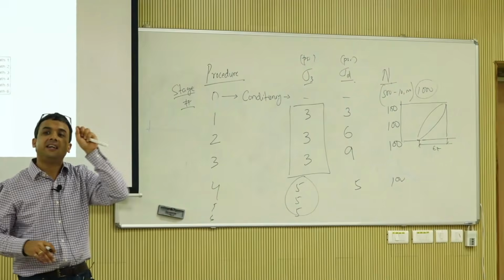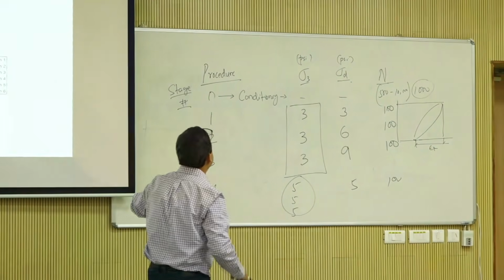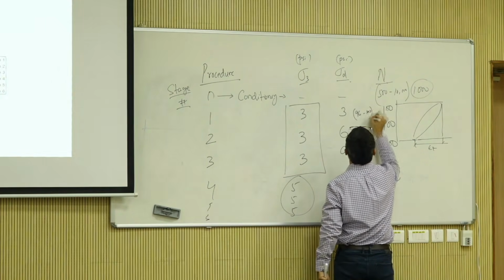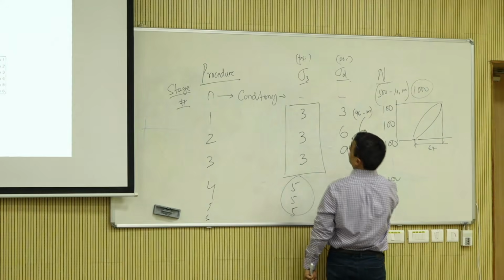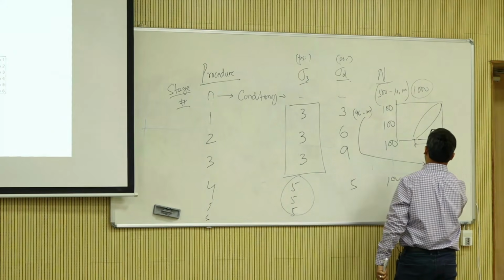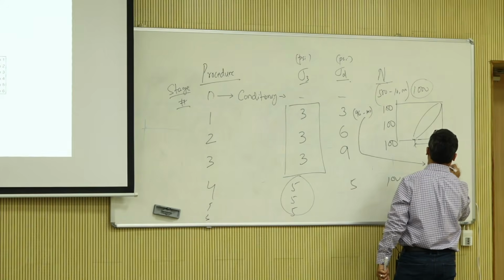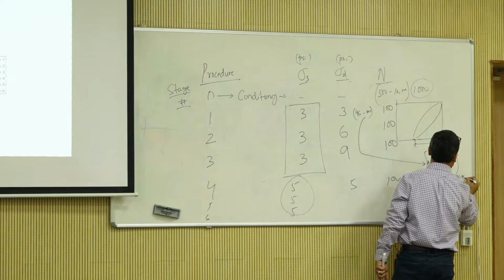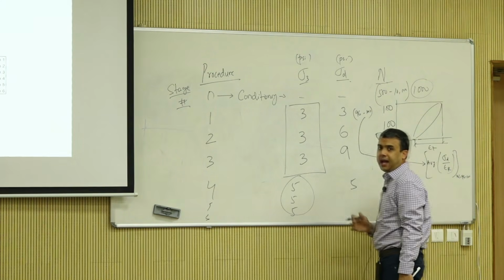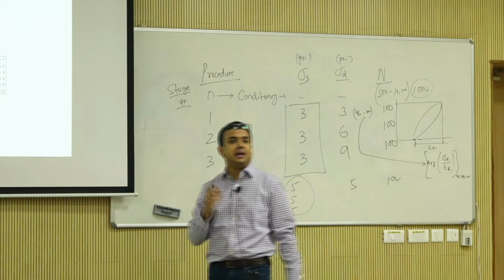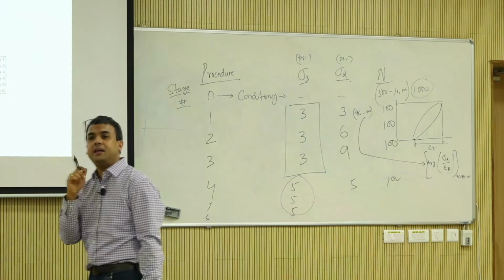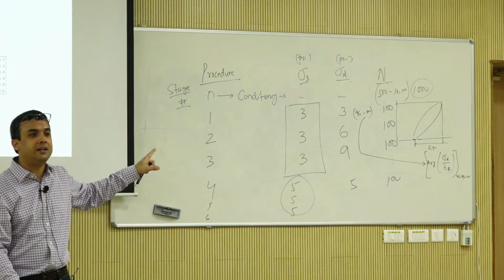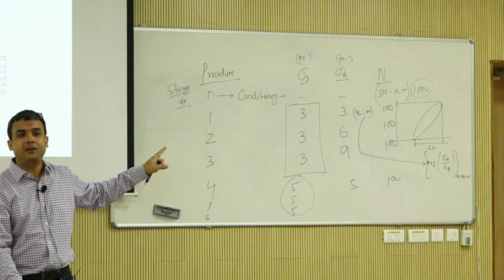For every cycle or for every stress sequence, you take cycles 96 through 100, take the average value of sigma d over epsilon r for each of those cycles, and that you report as your resilient modulus for that sequence. How many sequences are there? So how many resilient modulus values are there?